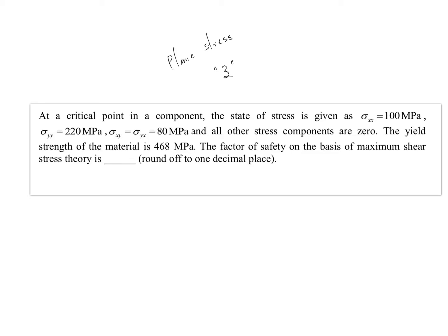Make sense? So I can invoke the Tresca criteria or the maximum shear stress criteria for the plane stress condition. To invoke this maximum shear stress theory, I should first find out the principal stresses in the three directions corresponding to this critical point. Let me call them sigma 1, sigma 2 and sigma 3.